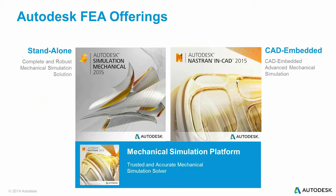On the mechanical finite element analysis offerings, we have a few products. There are two of them I'm going to focus on to start with. One is Nastran In-CAD, which is embedded in Inventor and SolidWorks, and the other one is Simulation Mechanical, which can be standalone but still launched from products like Inventor. We also have Autodesk Nastran, which requires a third-party pre- and post-processor like HyperMesh or FEMAP.